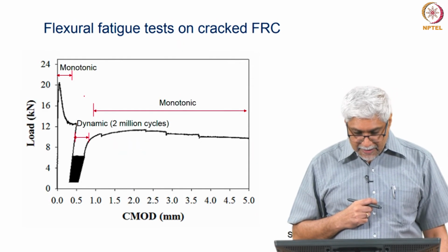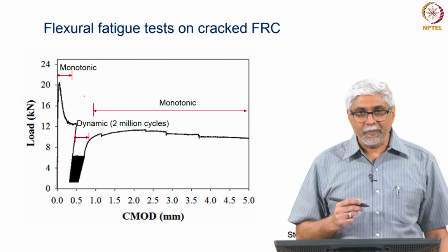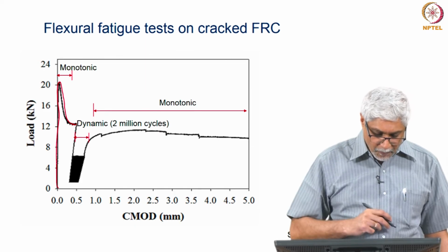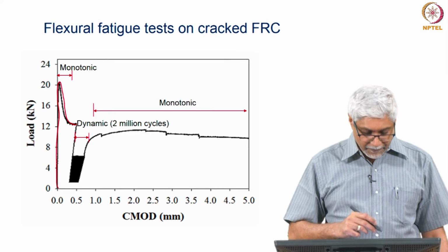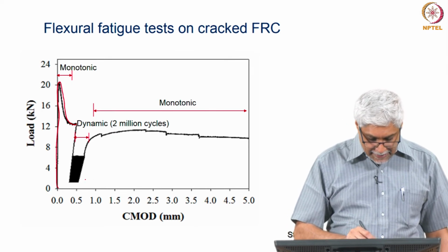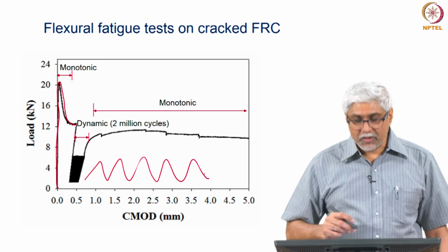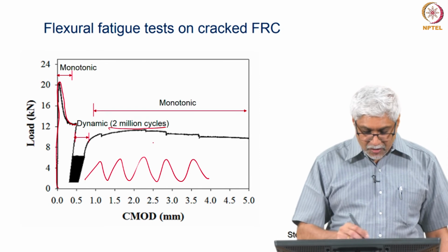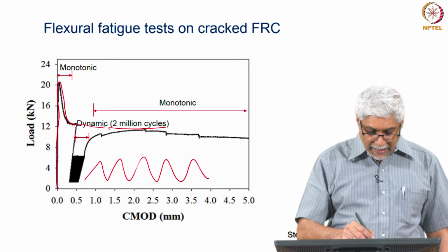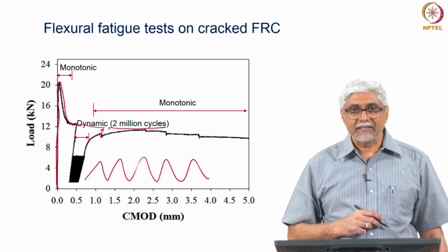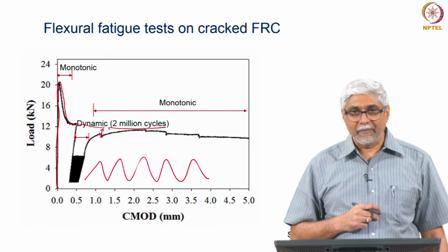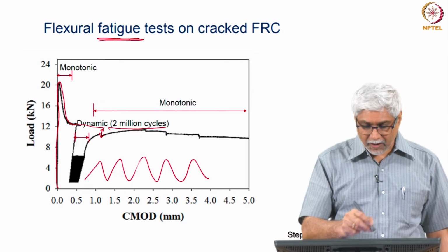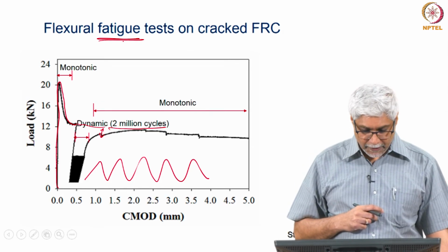So, these are tests from Steffi Stephen, where she is doing these notch beam tests with a monotonic part. She loads the specimen up to 0.5 millimeters of crack opening, then she does a lot of cyclic tests to see how fatigue is behaving. Then after about 2 million cycles she continues the test to see if the load carrying capacity has increased or decreased. Here you see for example that there is some residual damage. So, these are tests that tell us how the fatigue behavior of the concrete would be, in this case cracked fiber reinforced concrete.